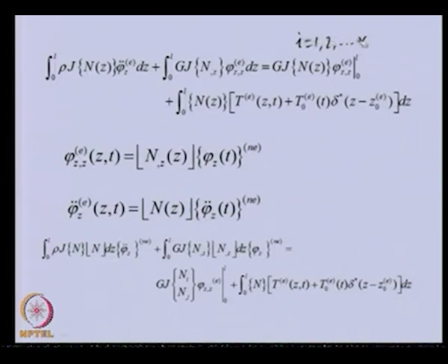Here r is 2 for the present case. So, this is the same weak formulation equation, where we put Ni in the form of a vector. You can see the form of N will be, for the present case, N1 and N2. So, if you expand it again, you will get two equations out of this.